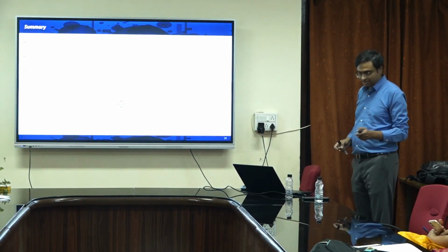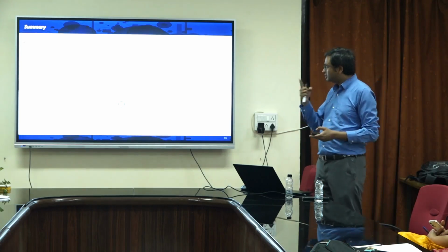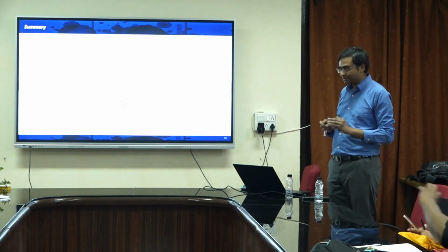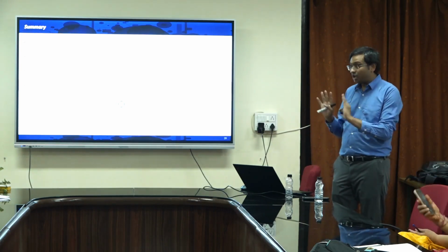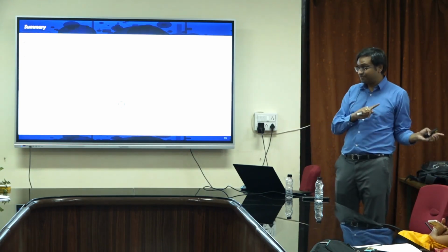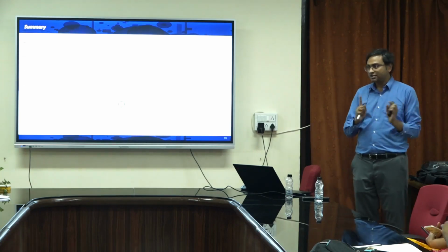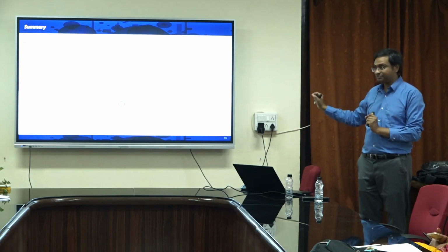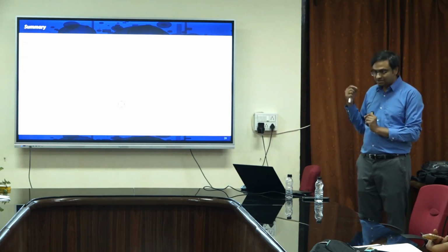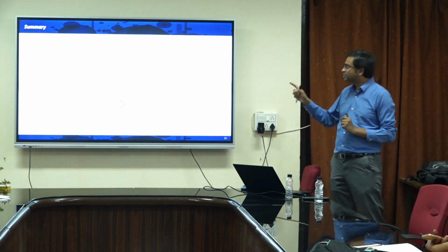But I think the take-home message from this lecture is that contact resistance for P-type 2D FET still remains high. Although we have achieved it, not 50 ohm micrometer, which was achieved for MoS2 for NFET, but for the PFET it is still high. It's of the order of hundreds of ohm micrometer. We still have a longer way to go.